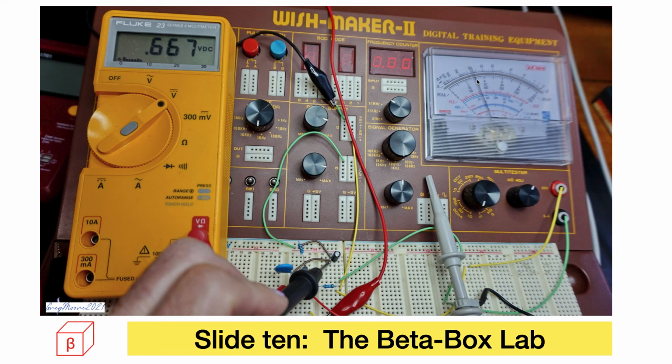2.74, 2.76, that meter, with the accuracy of the meter, is showing around about 3 milliamps of collector current. The voltage from the base to ground, 0.667. Well, no, sorry, I beg your pardon, that would be across the base, because here we have an emitter resistor. So 667 millivolts of base voltage in this device. Base emitter voltage, that would be base emitter.